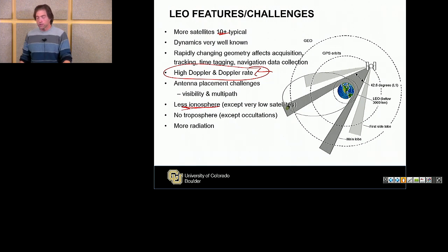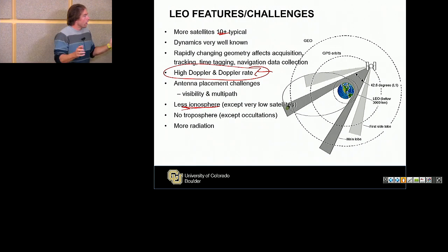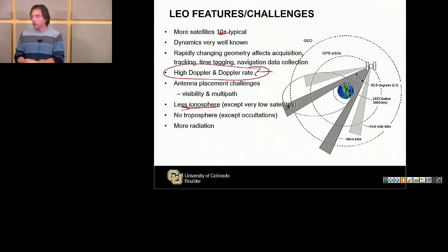So you can put a GPS receiver on a satellite for on the order of thousands of dollars to see really what happens. If I compare that to the JPL TriG Blackjack design, that is over a $1 million receiver, because for this remote sensing it's designed specifically for space and has redundancy, whereas the Novatel is never designed for radiation-tolerant work. But you can get a few-thousand-dollar L1-only receiver that kind of works in LEO.